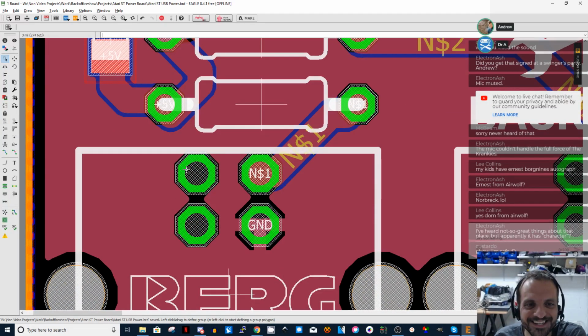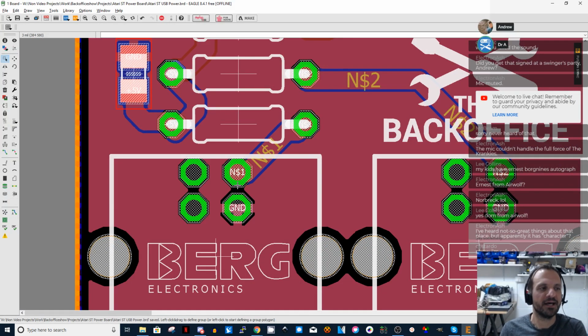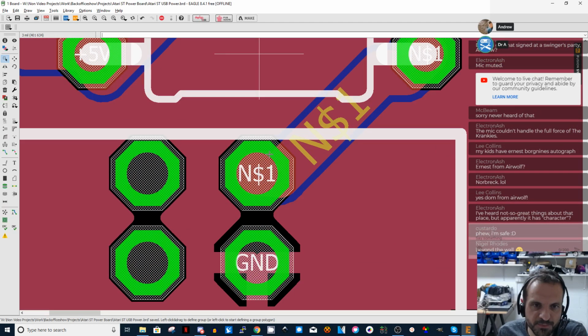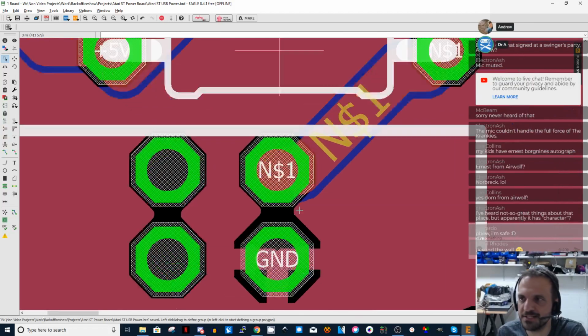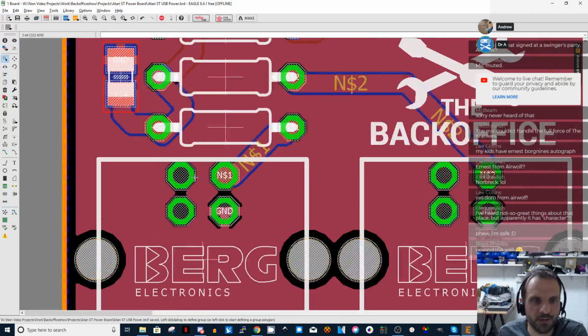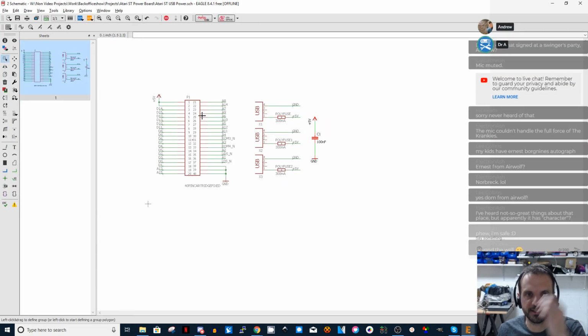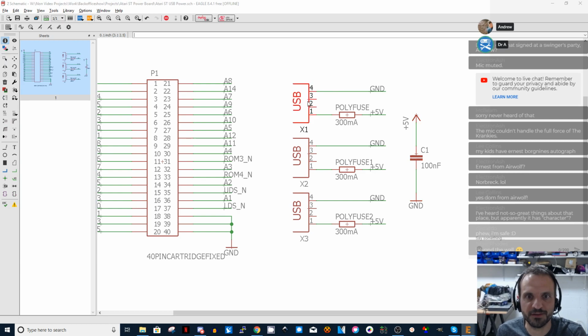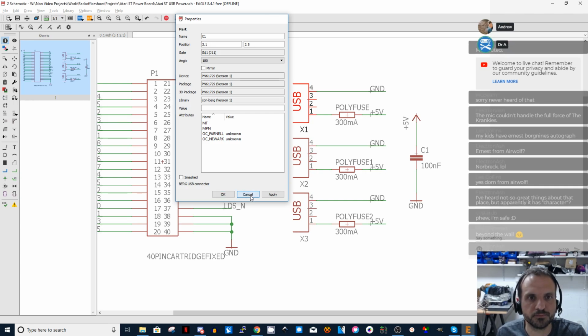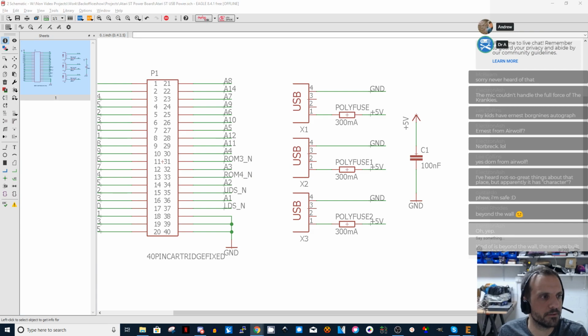Okay. These pins look wrong, don't they? Ash, look at these pins. Do they not look wrong to you? Because you've got 4 pins in the USB, mechanically. I wouldn't expect you to tap off 2 end pins by having 2 vertically adjacent pins here. I'm very, very worried at this point. I might need to get the part number for the Berg Electronics thing, and let's see what they actually have done with that stupid thing from the data sheet. Oh, it's got a Farnell part number? No, it does not.